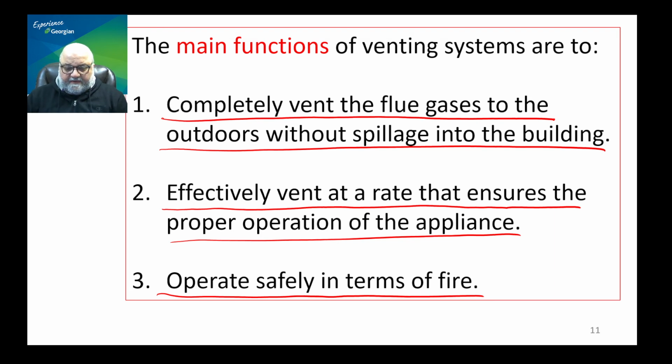A lot of venting systems are made of metal, and unless they are made of stainless steel, some of them are, others are just galvanized steel or whatever that can be corroded. Some of them are clay, or lined with a clay tile. Some of them are brick. Of course, those are going to deteriorate in time and create all kinds of hazards or unsafe operating conditions.